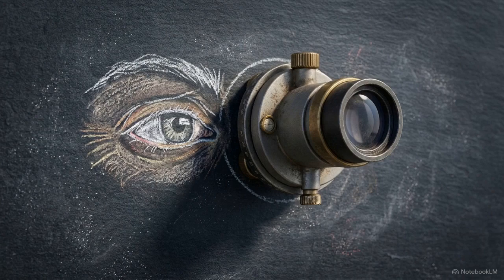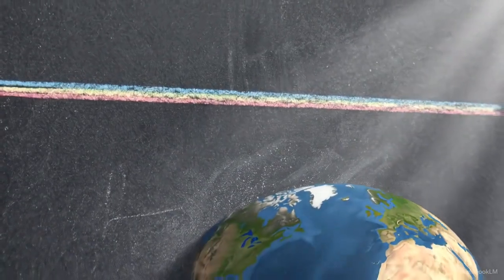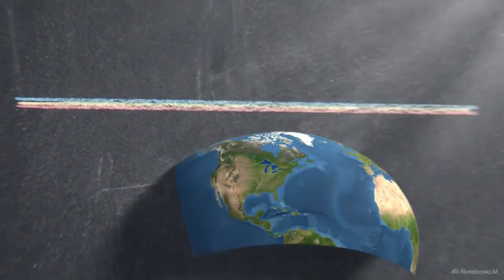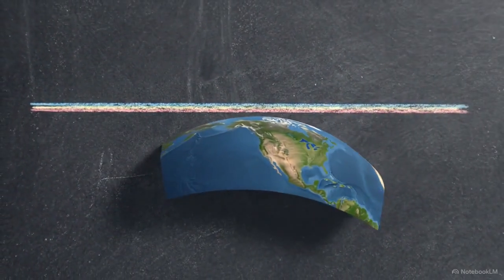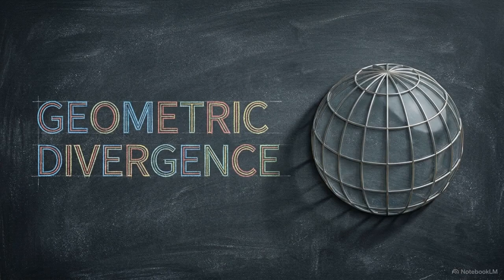When surveyors look through the lens of an optical level, they rely on a foundational premise. They assume the line of sight shooting out of the instrument is perfectly parallel to a flat, horizontal ground surface. But the Earth is a sphere. Over long distances, the physical ground drops away from that perfectly straight horizontal line of sight. This introduces the first systemic error in long-distance surveying.